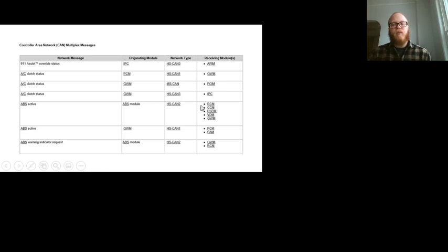Restraints control module, this is our airbag module. It has little accelerometers inside of it, so it helps the car know, is it sliding sideways or is it going straight ahead like it's supposed to be doing? Are we starting to spin? Is there a tilt going on? We can tell all that kind of stuff. We have our power steering control module. So power steering, do we want to maybe help steer the vehicle because we have electronic power steering systems now? Do we want to make it so that the steering is harder so that the customer can't overcorrect?